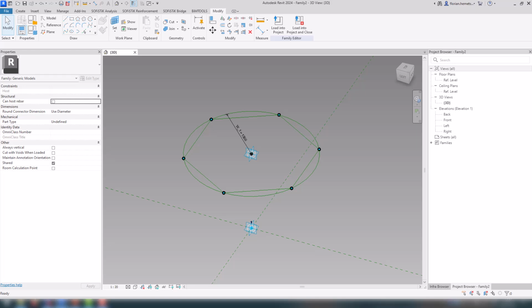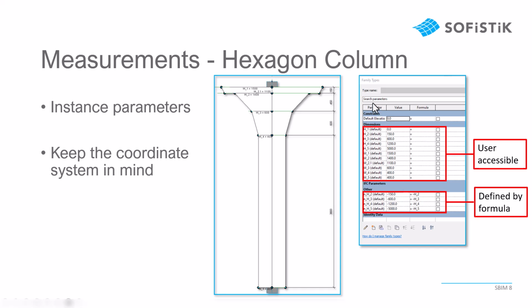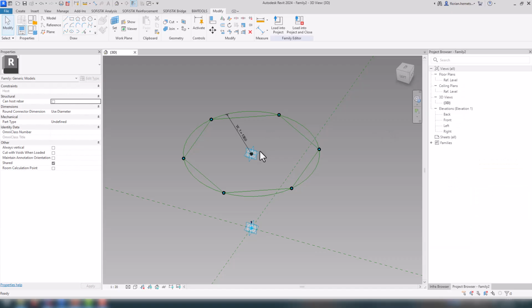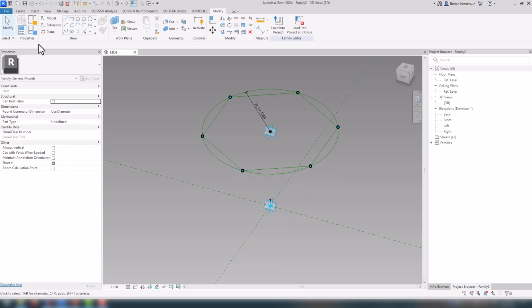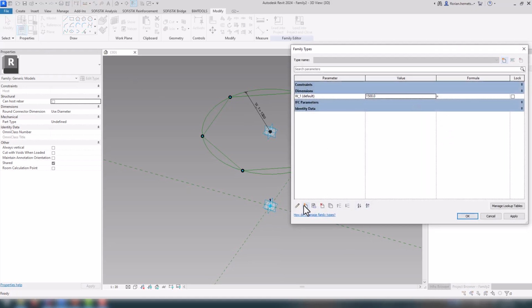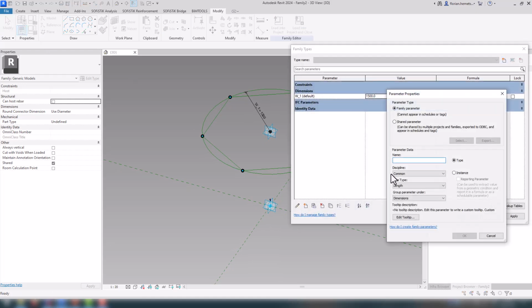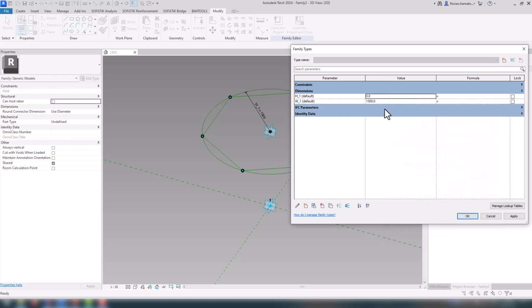All right, so let's take a quick look back at the parameters we want to create. We also see the height 1, height 2, height 3, height 4. But the first one we want to create is height 1 with 0, meaning the typical offset. We will create this parameter, select height 1, instance parameter, and this one is set to 0, which is fine by me.